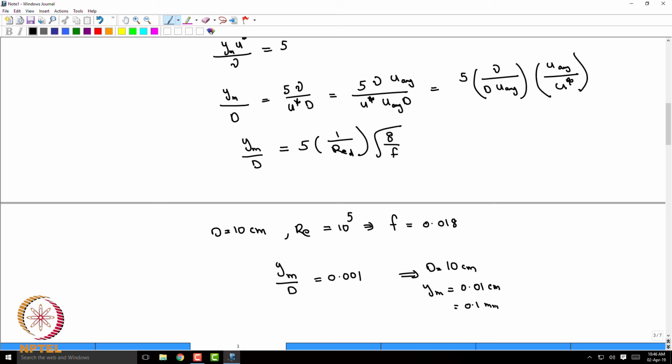So for the laminar flow, it's basically going all the way there, right? So there is nothing like a wall layer that is confined to the wall. There may be a small region where the roughness could affect it, but basically the viscous action will immediately smoothen it out because it's spanning all the way up to the radius. So that's why it does not get affected.